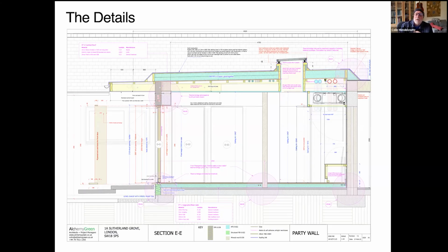Under this layer here is the airtight layer, which has got no penetrations. The OSB was fixed to the structure, and that had a layer of Alutrix on it, which is a super watertight and airtight barrier. And the underside of that forms the airtight layer.